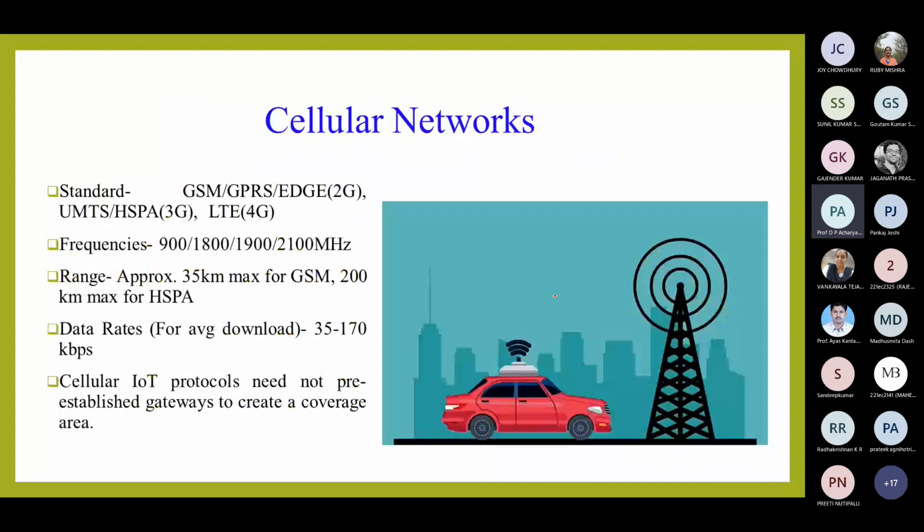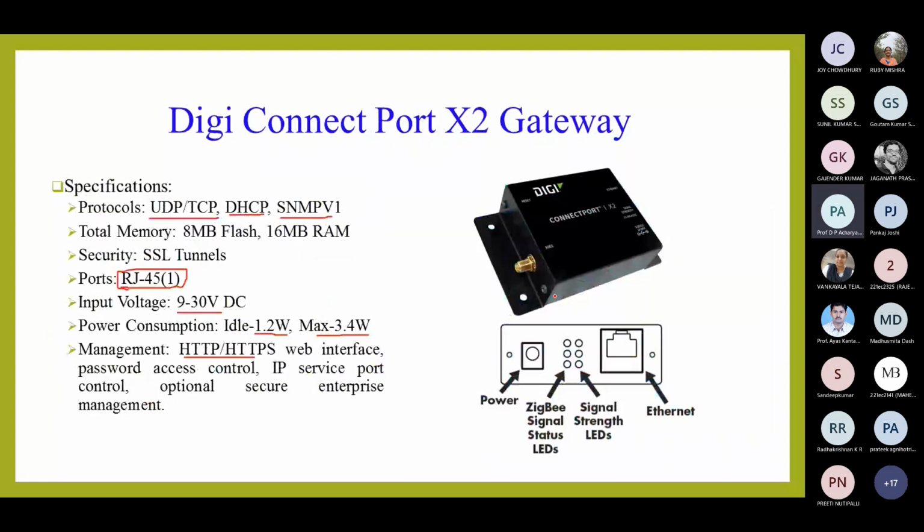Well, what I was trying to tell you is that Zigbee-based communications are more reliable than cellular communication, which will come next. The reliability is that so long as you are providing power to the Zigbee coordinator, and you are providing power to the Zigbee end devices and routers, you can expect them to be very reliable, in terms of not having failures.